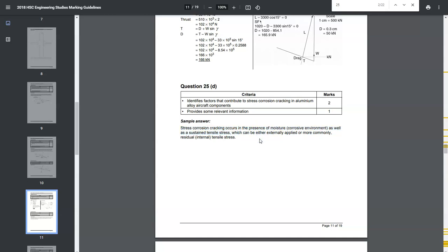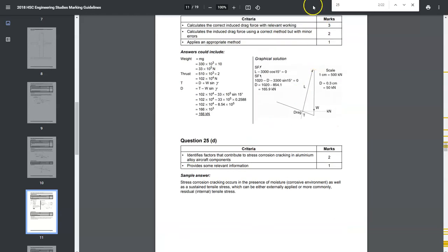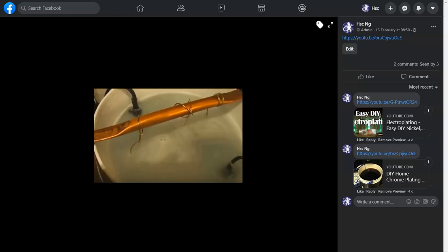Yeah. Okay, so what we're looking at here is you've got to think that planes have lots and lots of vibration because there's always going to be very small changes in air pressure around the plane, causing the plane to be moving the whole time, moving up and down. There's a lot of moving parts on a plane. So that creates areas of stress, and stress corrosion is more common in aviation because of the high moisture contents and the high levels of fatigue stress.